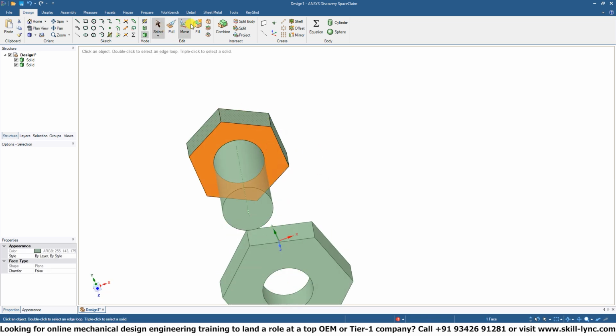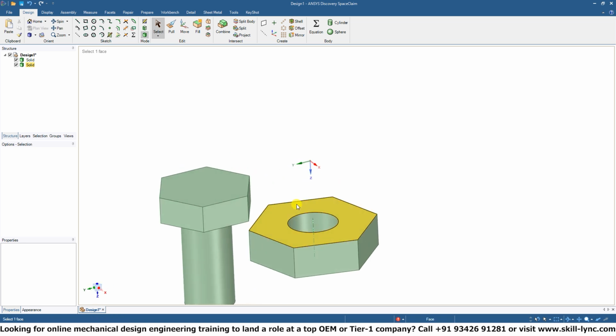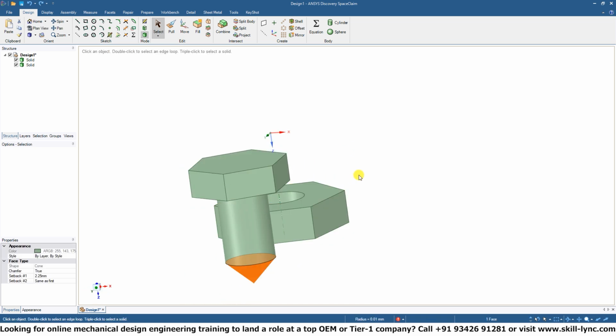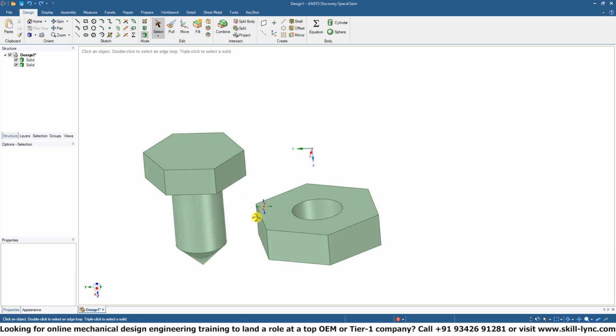Maybe if we click the fill tool over here, sometimes if we did an extruded cut from here all the way down, it might have been able to fill it back up, but obviously it's very limited in its application because it's a predictive tool. It tries to figure out what you're doing just based on some geometrical properties or previous actions that you've done. So it's not a sort-all, it's not a magic tool that can solve all of your problems.